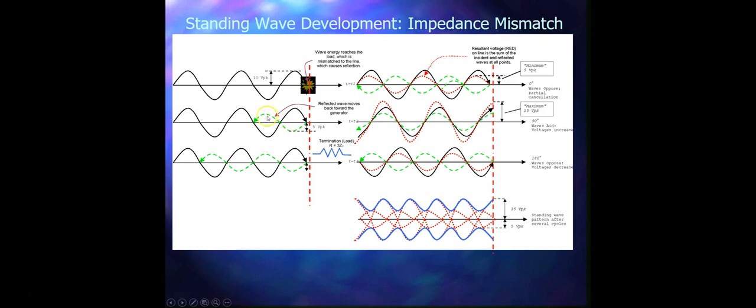So this reflected wave is traveling towards the generator side. In the third example, it shows how the reflected wave has further traveled. Here the impedance mismatch is R equals 3Z naught, where R is the load resistance, and it is 3 times the characteristic impedance Z naught.